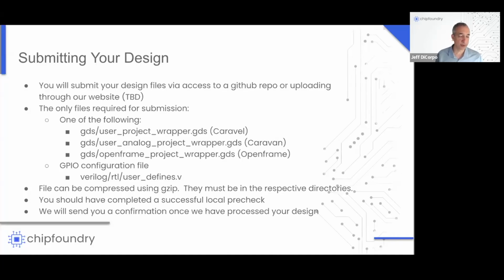So with respect to that, there's only a specific set of files required for submission. Namely, you need to provide us the GDS for your wrapper that Marwan showed. So that's depends on the SoC platform or frame you're using. There'll be a different file name for that. Also, you need to provide us a user defines file.